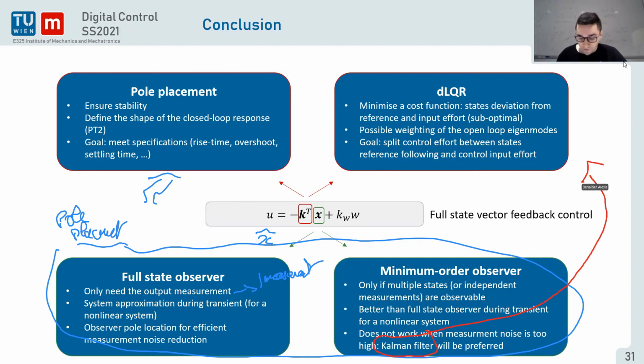So for the Kalman filter, we're designing the observer gain, which is called P, if I remember well, such that we're minimizing the cost function. And what we're minimizing is x minus x hat. Okay, so the integration or the summation, whatever. So this is just why I mentioned it here. The Kalman filter is a little bit more robust because it's considering the uncertainty of the measurement. Okay, so that was the last session.